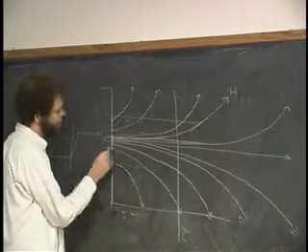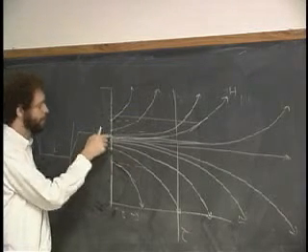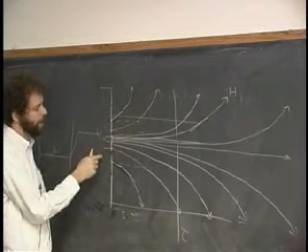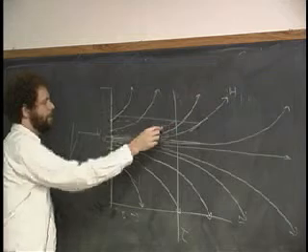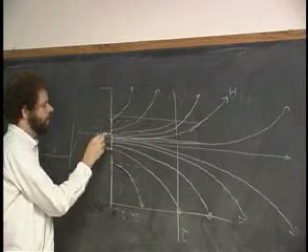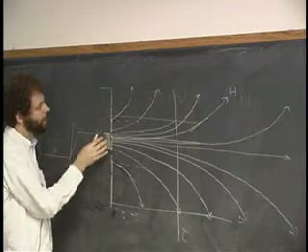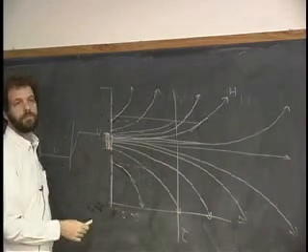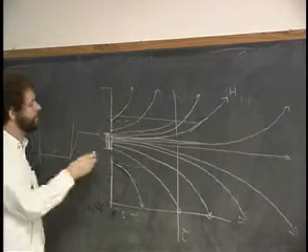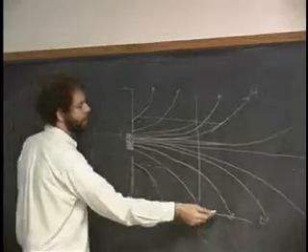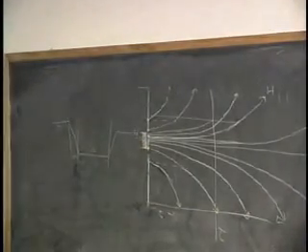And in fact, if I back up, if I say, what is V in when I start out? V in of 0 is the time here that I start. It's true that between this time and, if I back this out here, this time here, for all voltages inside of this range here, those will take longer. Okay? So that's all that this is saying here, is that Vn of 0 is e to the minus t over tau going backwards from here.